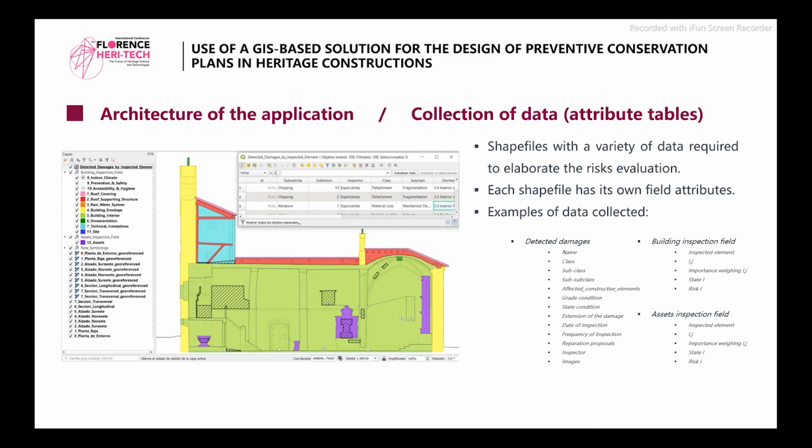Once the inspection has been done and the information is transferred into the computer program QGIS, the workflow for the risk evaluation can be established in a next step. All this data is collected and classified in several field attributes on each shapefile, defining the necessary data to elaborate the risk evaluation through the QGIS graphical modeler named Model Builder.